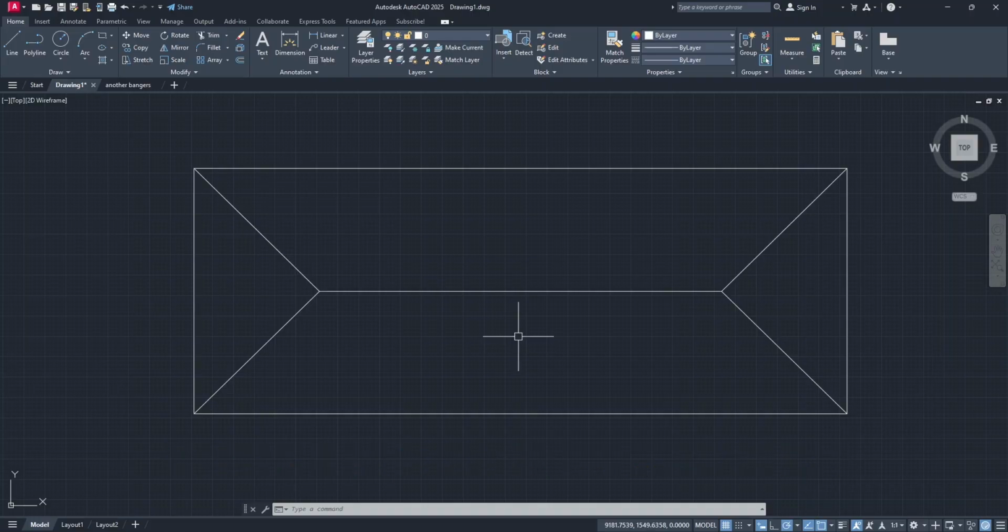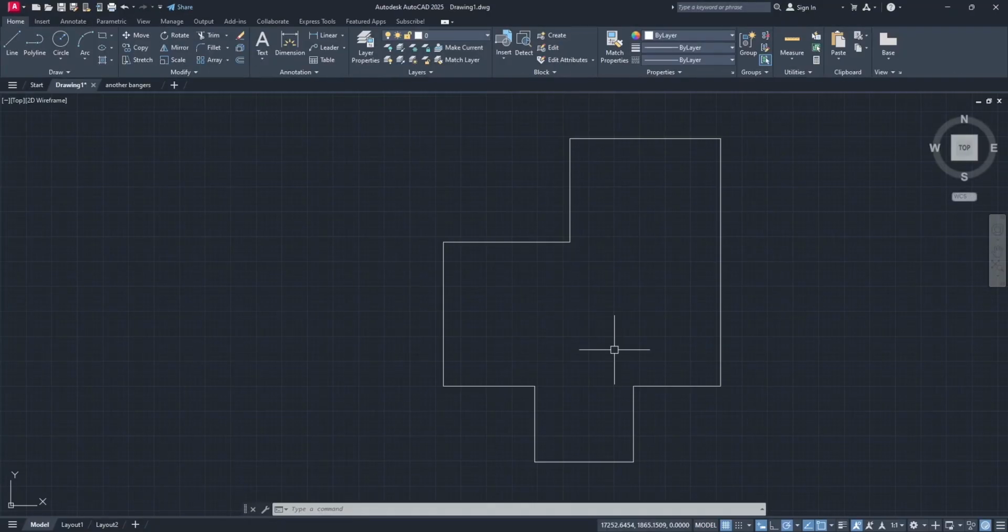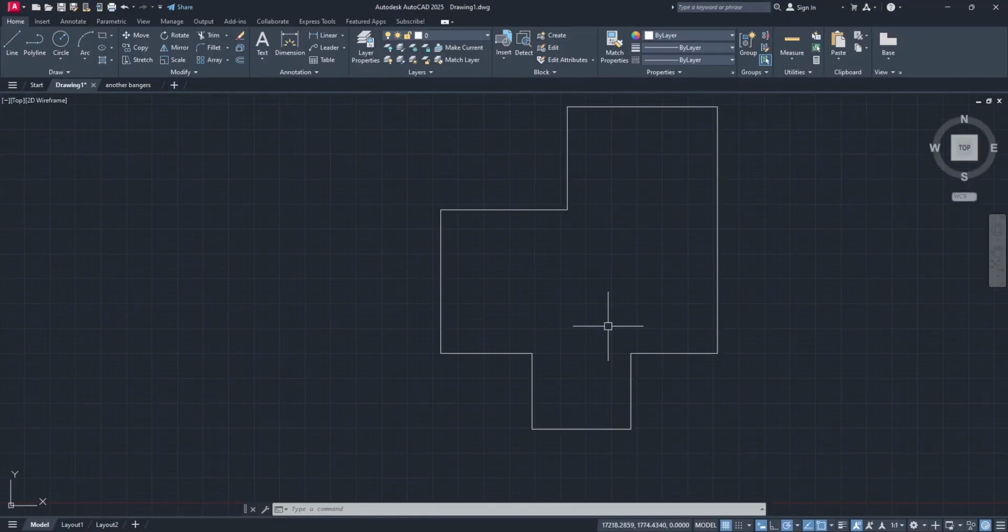And it's so much fun to draw. Now, if you have something like this, don't panic. All you are concerned with is to first create your hip end. Just select line. All you need is to make two. If I click here, point in this direction at 45 degrees and click, press enter.